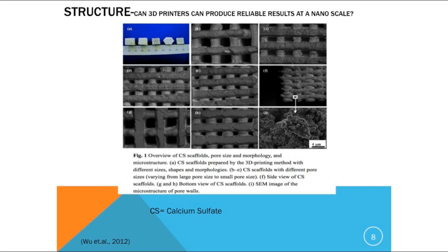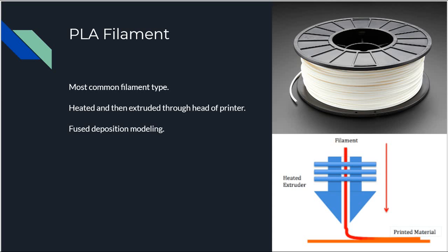These images show scanning electron microscope pictures of PLA filament, which is the material used by 3D printers to make objects. By looking at these pictures, you can see that the printer is capable of high accuracy when placing the material, which allows printed objects to be very detailed. In addition, the material is placed in layers, which makes it possible to make many structures that otherwise couldn't be made. The most commonly used filament for 3D printing is polylactic acid, and it comes in large spools or in a pellet form for industrial use.